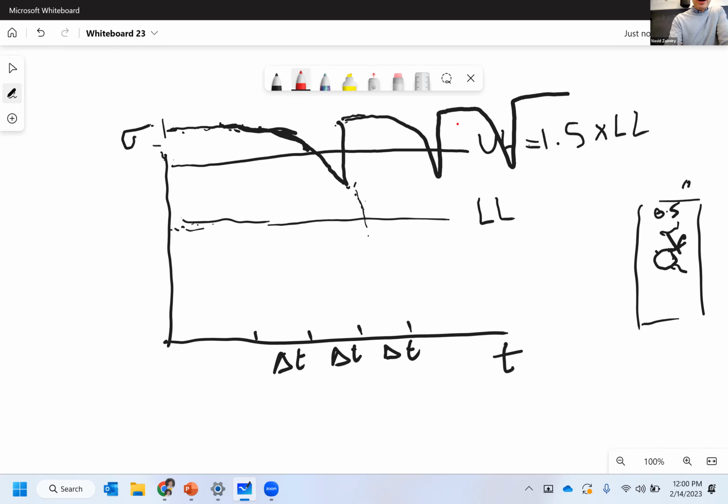Okay. So now let's see how a composite structure works. Let's say it's more or less the same strengths. And composite don't experience fatigue the same way metals experience. They do experience fatigue, but it's extremely slow. So if you look at it, the slope that it goes down is extremely slow, and it doesn't happen in the speed that happens for metal. So fatigue is an issue for composite, but it's not a major issue.